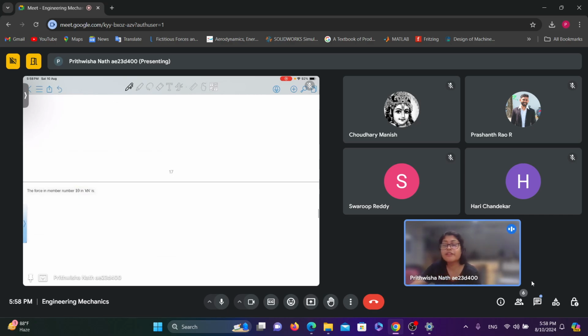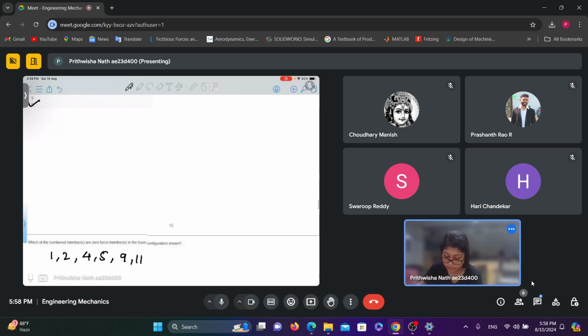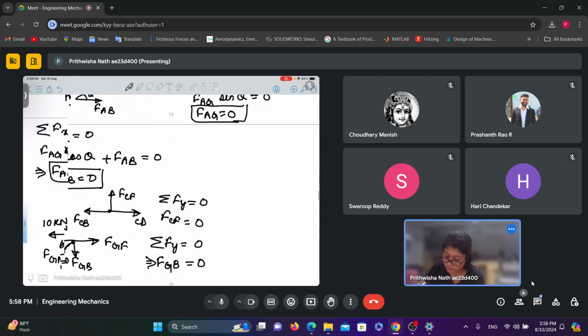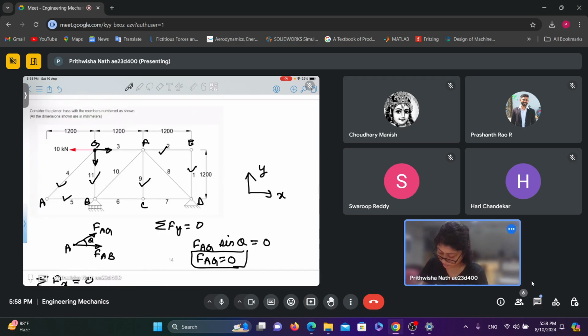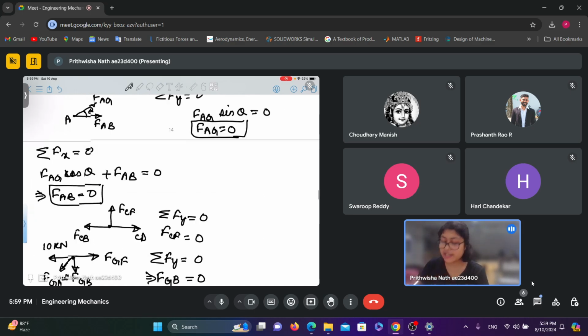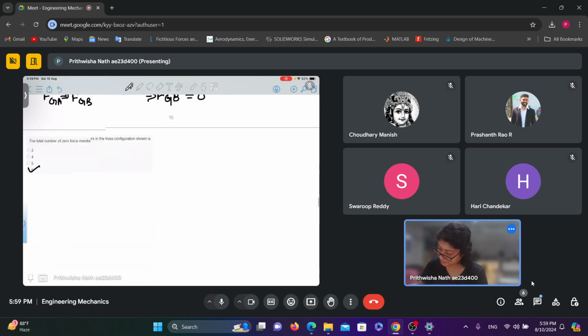Now the next part of the question, the force in member number 10. This is member 10. We need to find out the force in this member. Now I'll consider the joint at B.